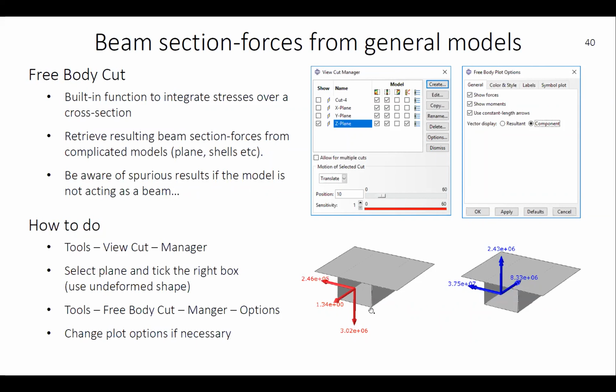But what it does is integrate the stresses in your model. So if you have any stress concentration or local defects in your model causing unwanted stress concentration, that will be included in the integration. So you may have rather spurious results in those regions, especially, say, at support conditions if you model those in an inappropriate way or have other kinds of stress concentrations.